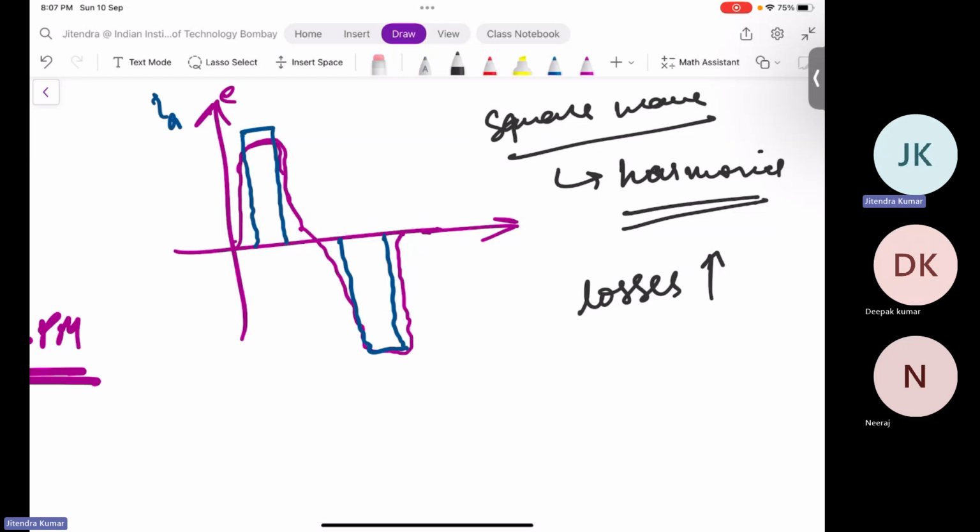Compared to AC machines, where you have sinusoidal current, so zero harmonics in current. But some harmonics will still be there in AC machines because of the winding MMF or space harmonics. But you are reducing them from the supply side, and that's where you gain, and that's why we use PMSM for high-end electric vehicle applications, premium electric vehicle applications. For e-rickshaws, three-wheelers and two-wheelers, we use BLDC.